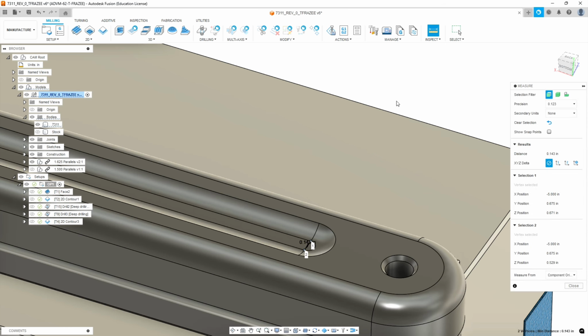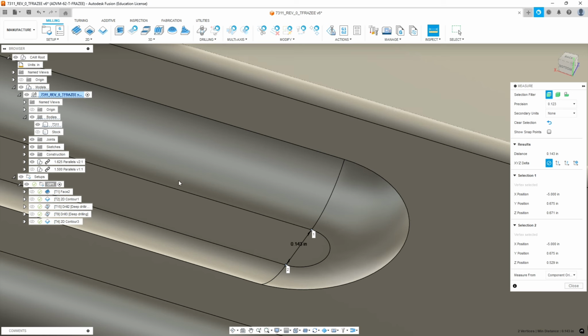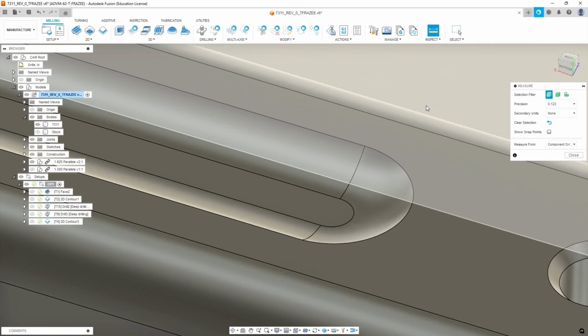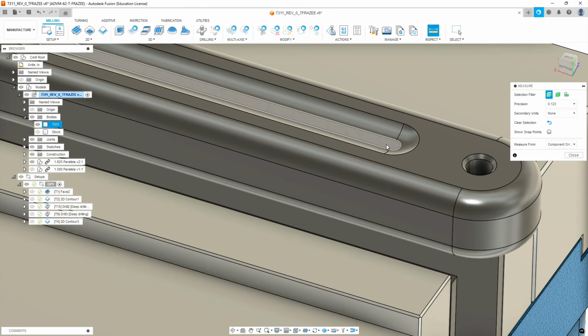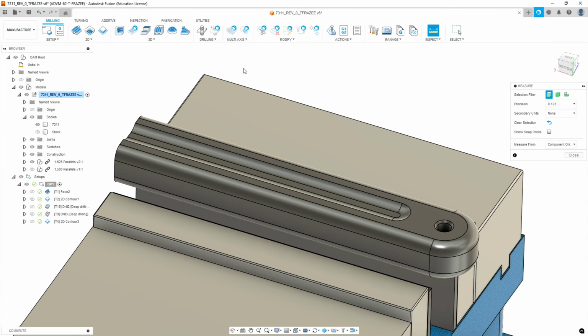If we had an 1/8 inch flat end mill, it could cut this pocket, and then we would come back and cut the ball shape with a 1/2 inch ball. So we're going to end up having to surface this, which takes up machine time. All right, so there's a couple different ways we can approach this, but we're going to do a roughing cut and then a finishing cut.